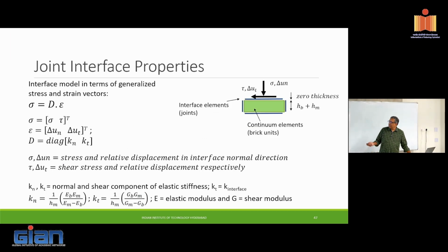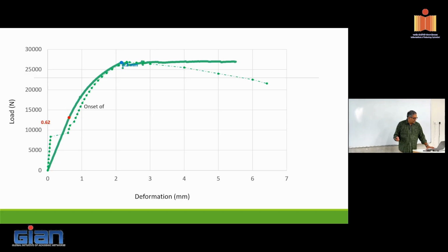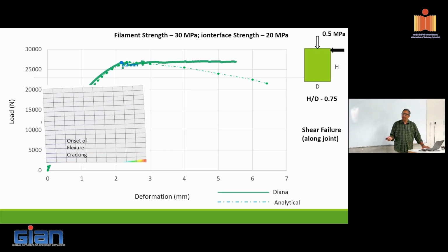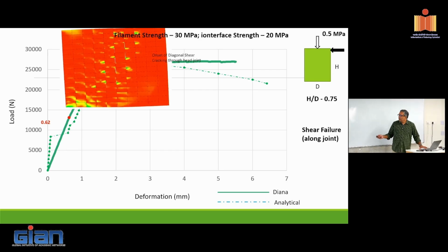I will not bore you with this, but there are enough micro level models in literature, where you can port from plasticity, you can use different formulations where you essentially go down to Coulomb's friction mode of failure, which is basically a combined shear and compressive stress failure. And you can formulate a failure surface for the masonry. And just like what we would do in masonry, here I'm gloating a bit because we've actually done the simulations for masonry.